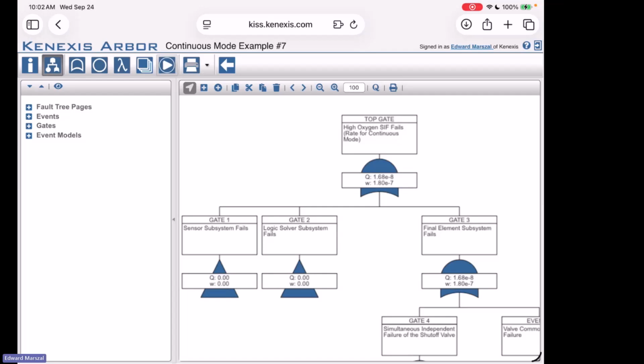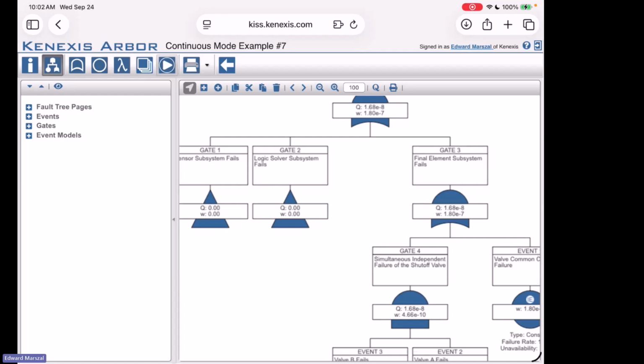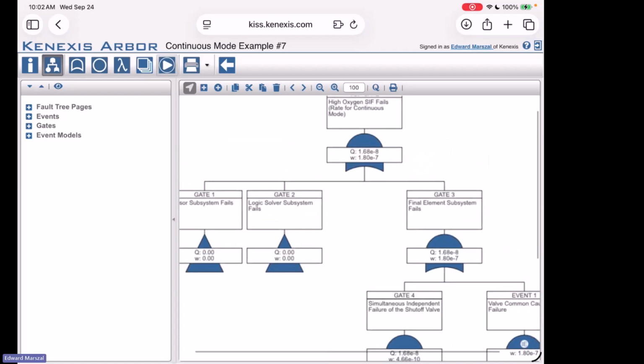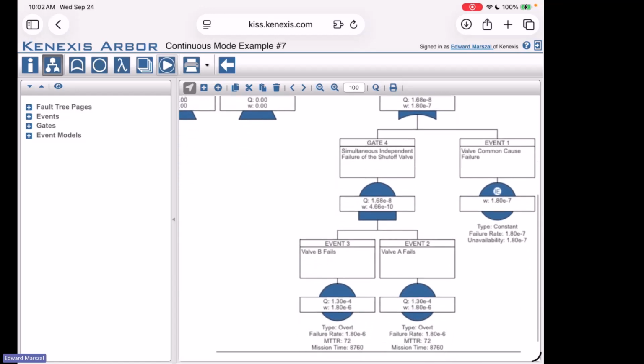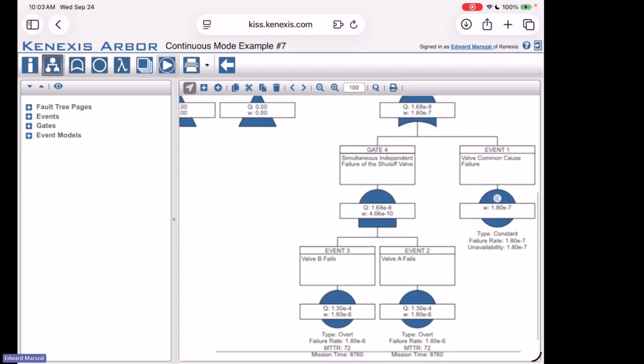You don't have that periodic proof test. So getting into SIL 2, even without doing a lot of redundancy all along the way, is probably not even going to be possible. But with that, that kind of is my spiel for today.